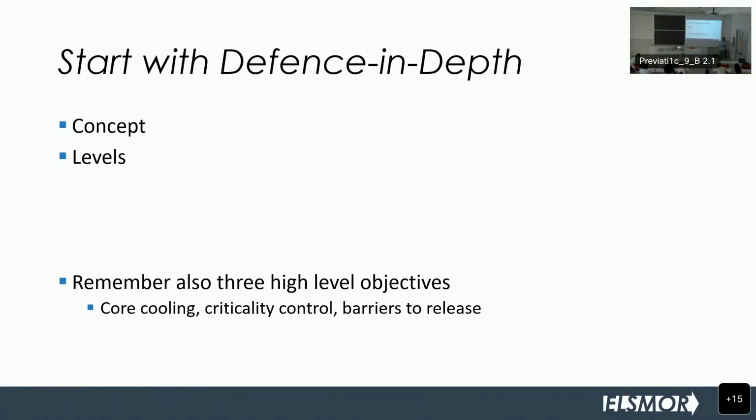We have systems that control the normal operation. We need to have systems that, if something off-normal happens, bring the system back to normal operation. And if this fails, we need systems that control that accidents do not cause any damage. And even if these systems fail, we need systems to control the damage of these accidents. So basically, we have successive barriers, and this is also what these different levels are.